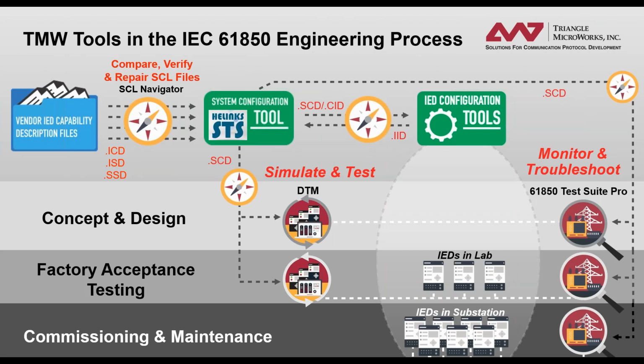Okay, next question. If you build the HMI logical node, where will this reside in an actual implementation? What IED? Well, the HMI logical node in the substation section typically will reside probably at the station level. But then the HMI itself is at the end of the day also an IED in the system, like every other IED. It's probably an IED that has only a client, but it still appears in an IED section as an IED, and the HMI that is part of the specification will refer to that HMI logical node in the IED.